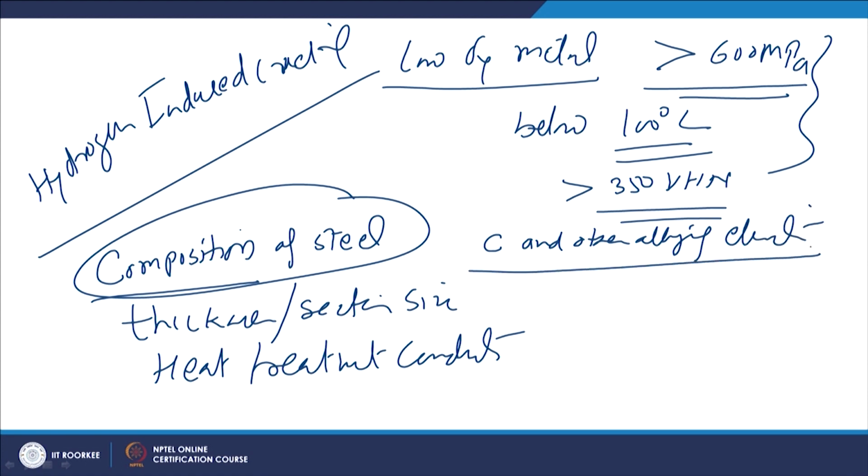So, carbon directly increases the hardenability. To account for the effect of other alloying elements similar to that of carbon, a parameter called carbon equivalent is calculated. When the carbon equivalent is calculated, it gives us an idea about the hardenability which will be shown by a given steel, and that in turn determines the ease of welding, or the weldability.